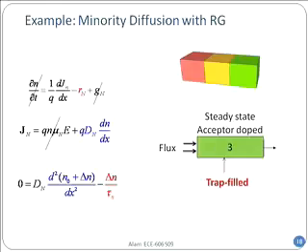Remember, I was asking the question, how come in high injection the recombination looks smaller? So under appropriate conditions, you will have to replace it with appropriate expressions for recombination, right? If it's direct recombination, you'll put the direct recombination term in, B multiplied by delta n. So whatever it is, as I tell you from the problem, you should be able to pick it up and put it there.